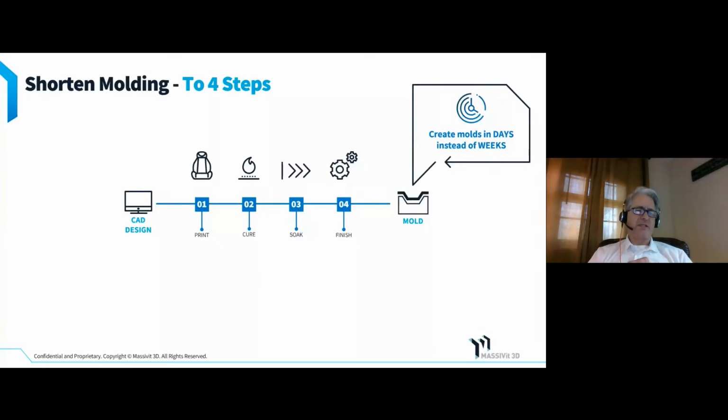You can hand sand it to get down the rough edges, the high spots. And then we are developing a coating process where you can spray coat something similar to automotive paint. It lays down like a paint. It air dries, and you can achieve with the painting and very little buffing and polishing a Class A mold finish.